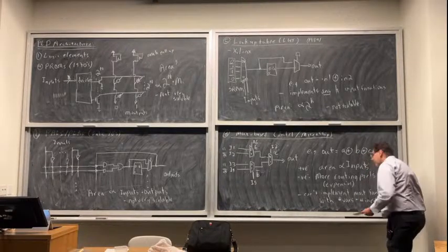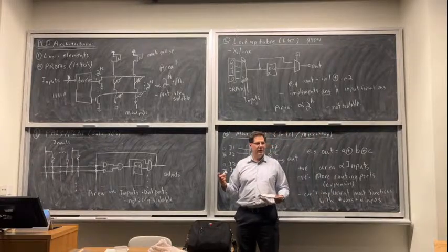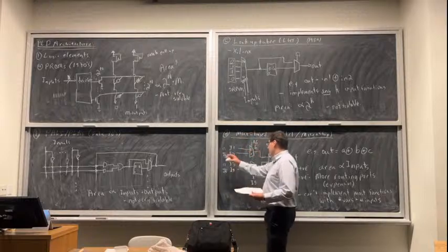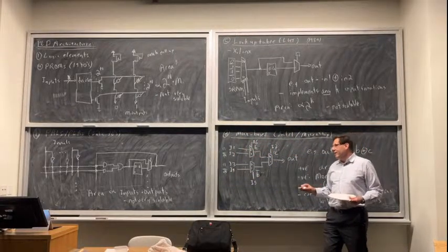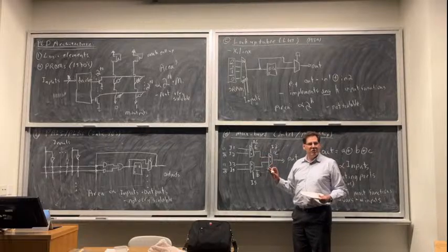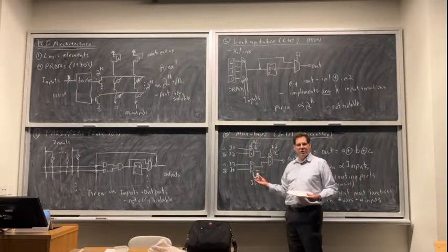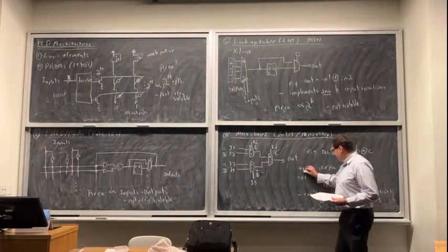This actually has 7 inputs, and it can't do very many 7-input functions. It can do multiplexing, like a 7-input mux, or a 4-to-1 mux, which is a useful function, but there aren't that many other 7-input functions that it can actually do. That would be fine, except for the fact that these inputs are expensive.